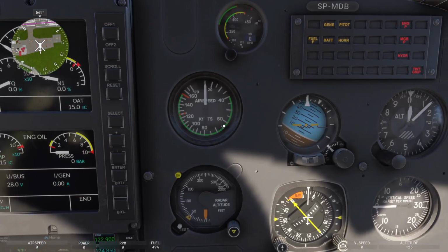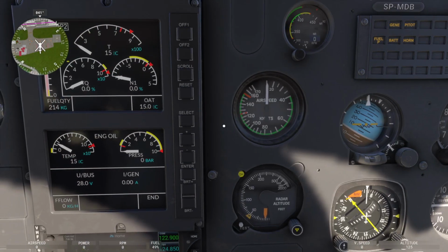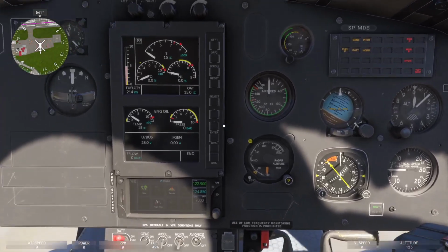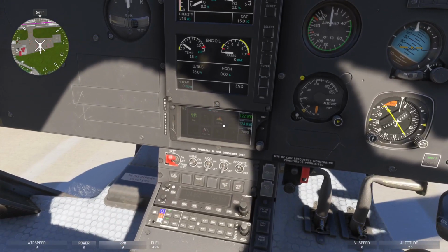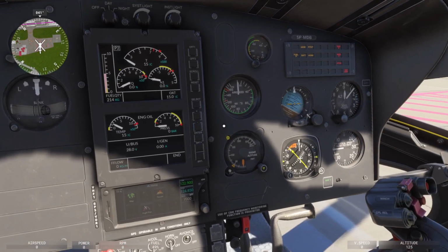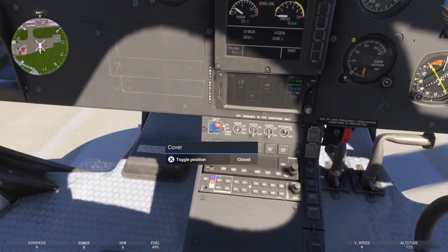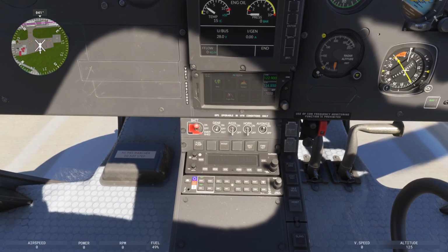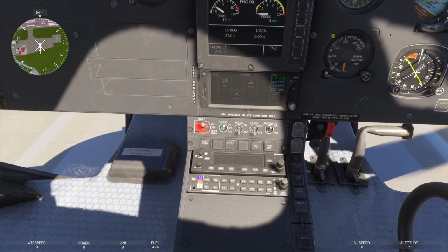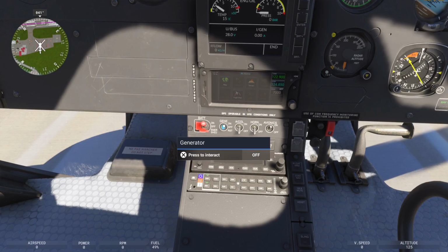On a Cessna, on the 172, I think it's different, which is actually right, because that is three-phase AC. On a Cessna, I know that the attitude indicator was alive. But AC, battery creates DC, it's never going to work, unless you have a standby, like an emergency system. You can get those. You can get rectifiers, which are 28 volts DC driven.